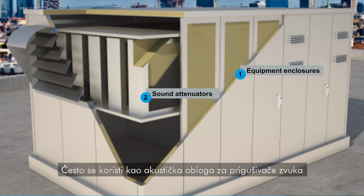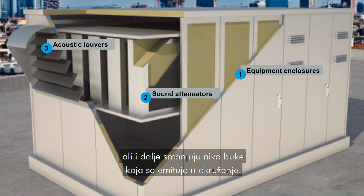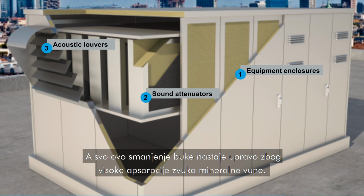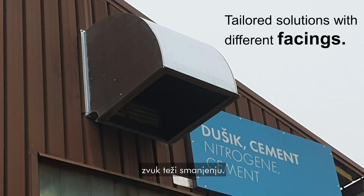It's often used as the acoustic infill for sound attenuators, or inside acoustic louvers, which enable the circulation of air but still reduce the noise level which we emit into the environment. And all this noise reduction happens exactly because of the high sound absorption that mineral wool provides. Because as we force the air and the sound to go through a certain space which is lined with mineral wool, the sound tends to get reduced.